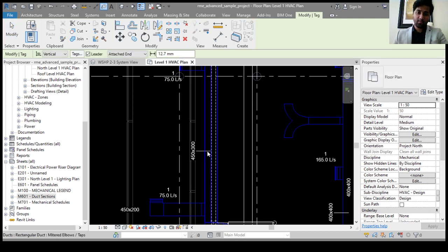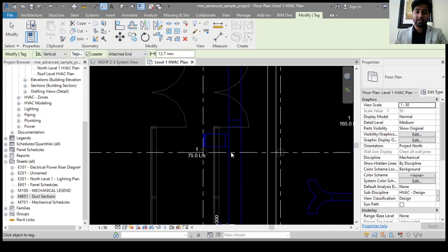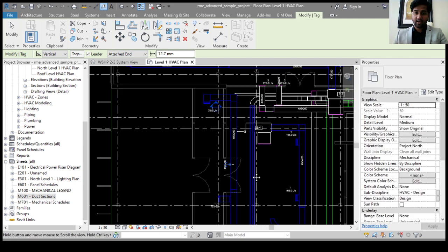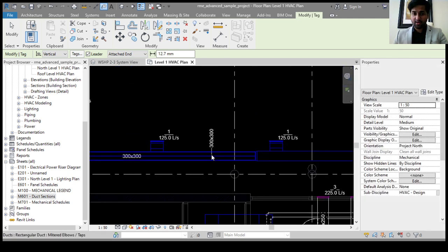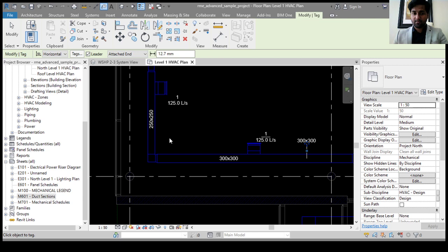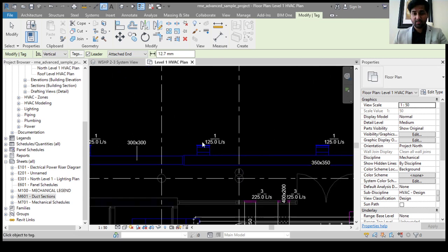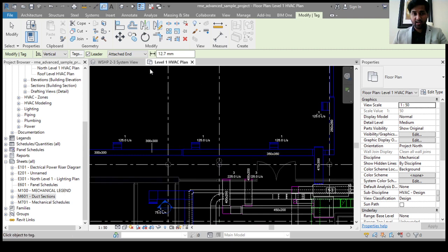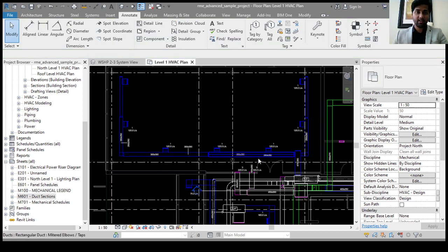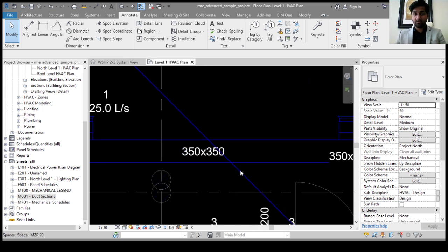as you can see, what I'm getting is the size of each duct which I click on. And you can see it's very quick. We don't need to spend a lot of time clicking on each duct and checking the size of it. You can easily provide tags with leader or without leader as you wish, and it will be accurate according to your drawing. That makes it very quick for Revit to create detailed drawings, right?